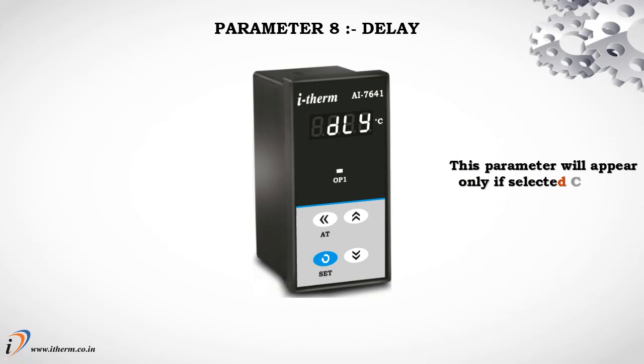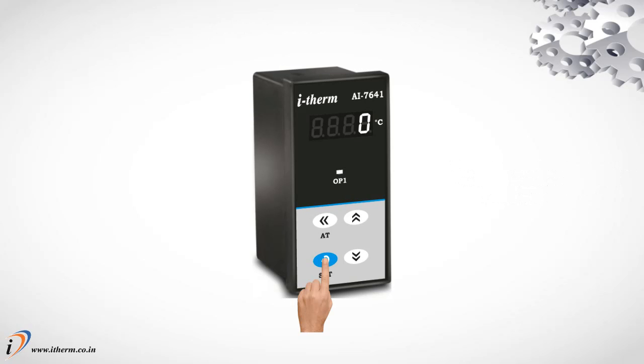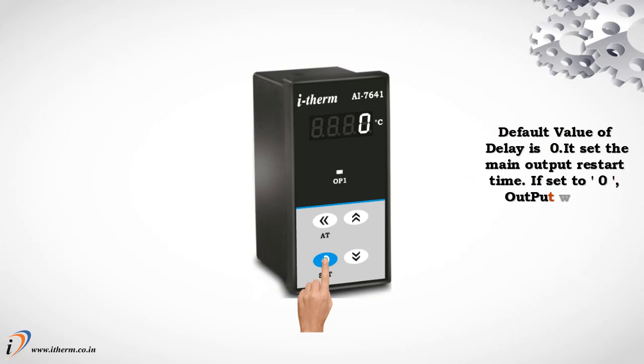Parameter 8, delay. This parameter will appear only if the selected control action is on-off. Default value of delay is 0. It sets the main output restart time. If set to 0, the output will be switched without delay.